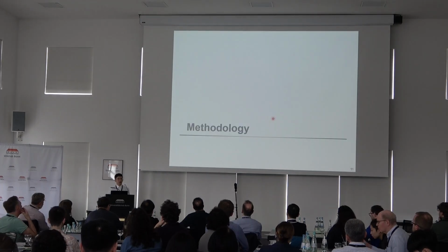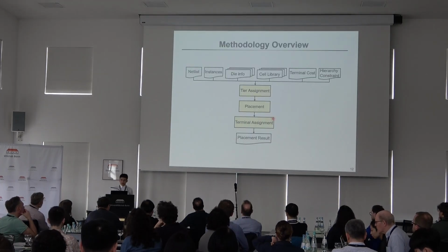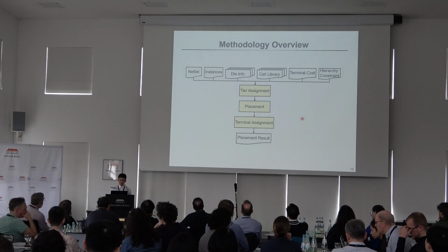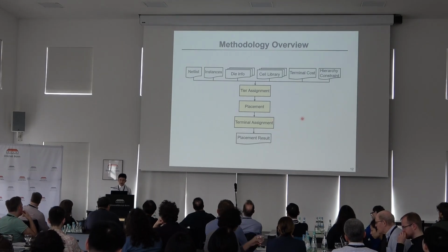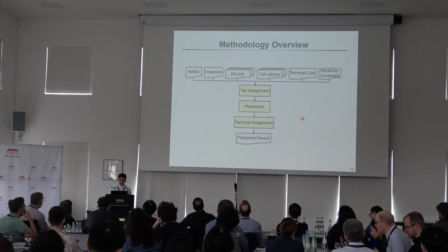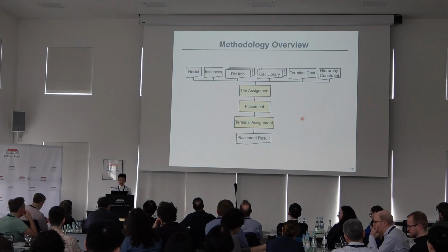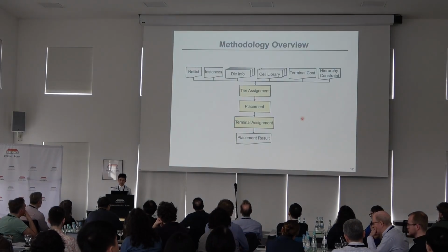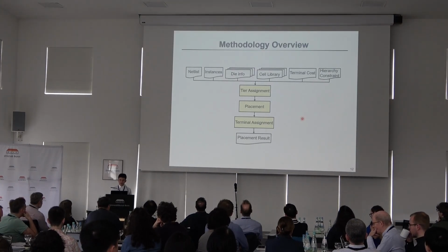Now we go to methodology. This slide shows the overview of our methodology. After parsing all the input data, we first perform tier assignment for all instances. Then we solve the placement problem sequentially for each tier. When all the instance locations are fixed, we apply terminal assignment to place the terminals and finalize the placement.